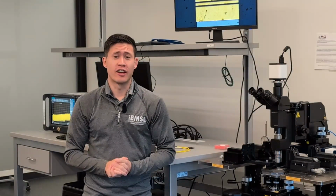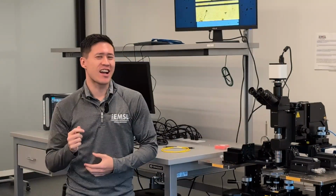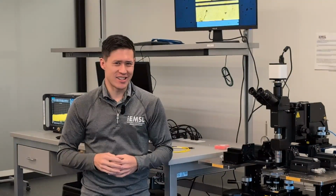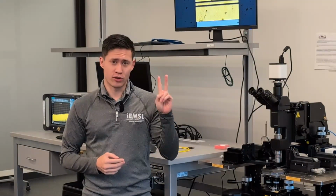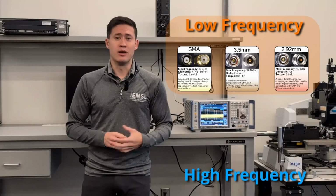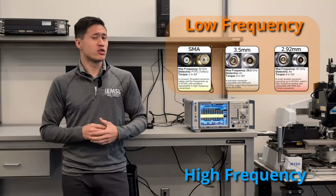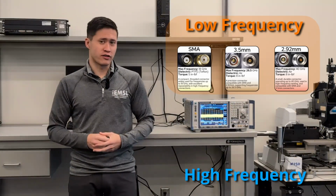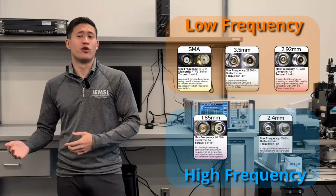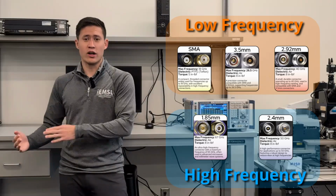Now, let's take a look at all the coaxial connectors that have this hexagonal coupling nut on them. Although they all seem to have the same overall size, we can't connect them willy-nilly to each other. There are 2 compatibility groups here, which I'll call low frequency and high frequency. The low frequency connectors are SMA, 3.5, and 2.92 millimeter. In a pinch, you can connect all of these components to each other as long as you have the correct gender of connectors. In the high frequency group, 1.85 and 2.4 millimeter connectors will mate with each other as well.